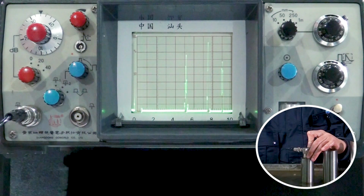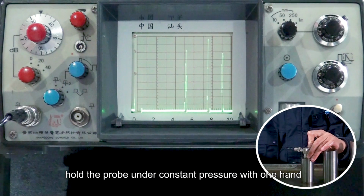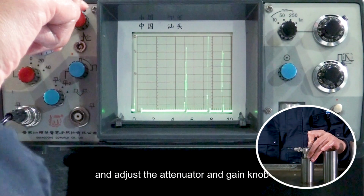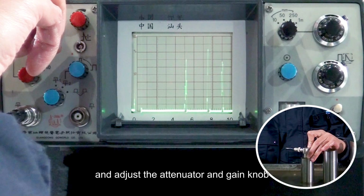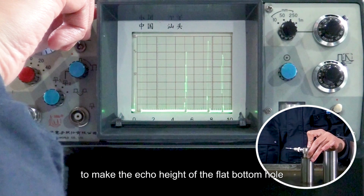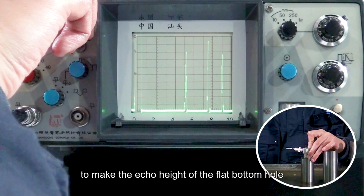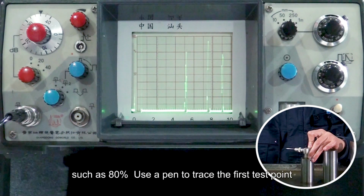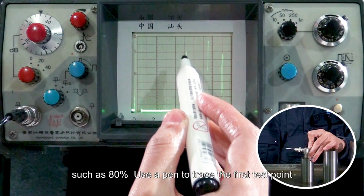At this time, hold the probe under constant pressure with one hand and adjust the attenuator and gain knob of the instrument with the other hand to make the echo height of the flat bottom hole just reach the reference wave height, such as 80%.